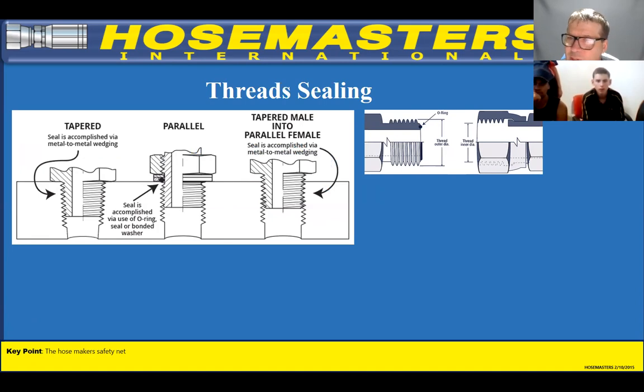But in today's world, that's not the way it's going to go. Each job is a separate job. You anchor, you seal. Does that make sense to both of you? Yeah. Now, what it's saying here is you can actually put a taper fitting in a parallel hole and it will seal, but it'll screw the hole up because it distorts the threads. So a lot of times people will say, oh, you can do that. Yeah, you can do that, but just be aware you're going to screw up whatever you're screwing into. Does that make sense?